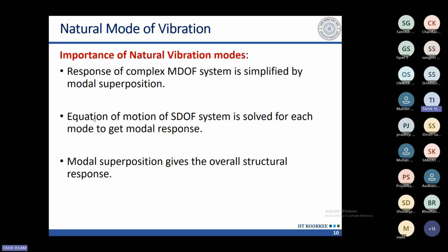So what we do, we solve the equation of motion for the single degree of freedom system for each mode to get the modal response. Then we do modal superposition to get the structural response. Okay. So now you understand the basis of our structural analysis using any software.